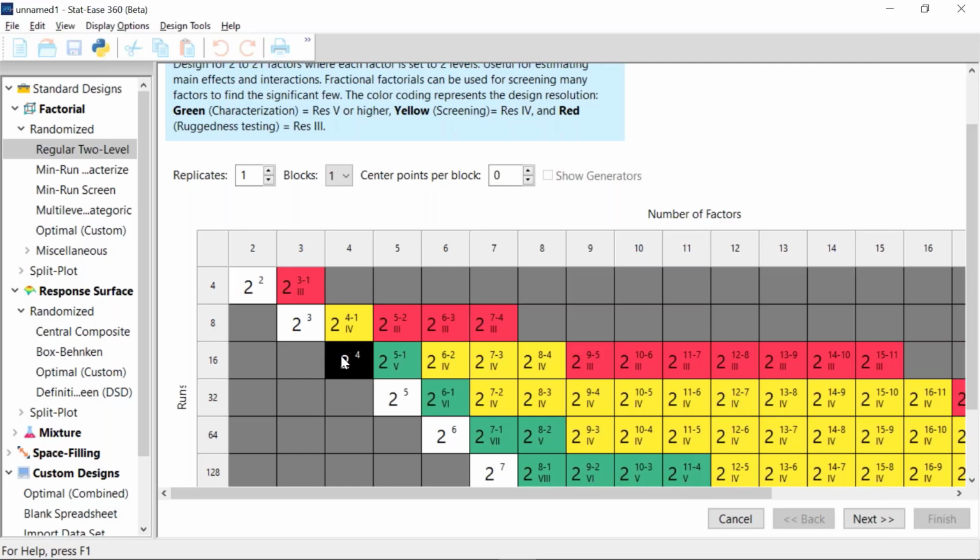I would look at various things that the organic chemist provided as a starting point, and then gradually scale up from bench, through the pilot plant up to the manufacturing site. And one of the nice abilities we have with this design builder is we can do what are called fractional 2-level designs. And because of the color coding, we can see what the quality of it is.